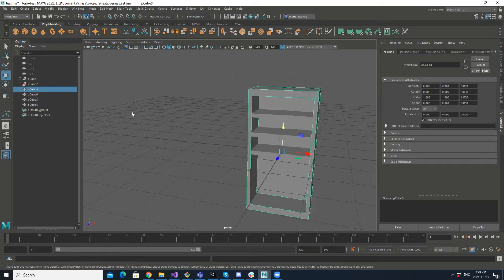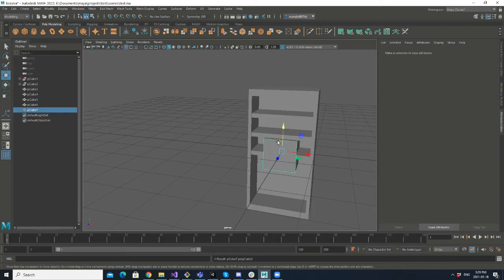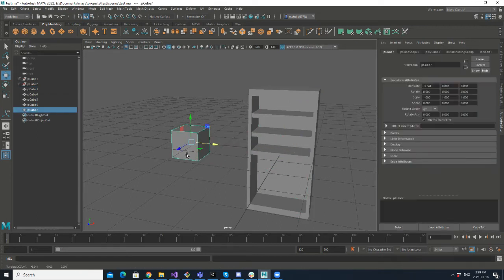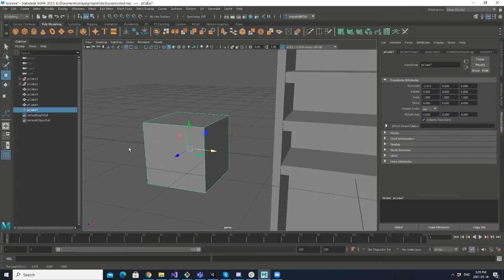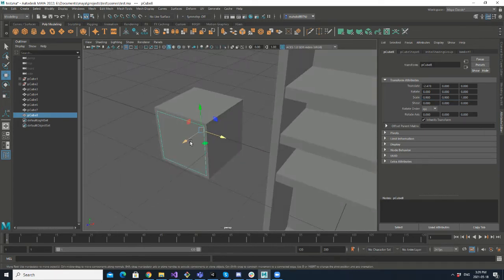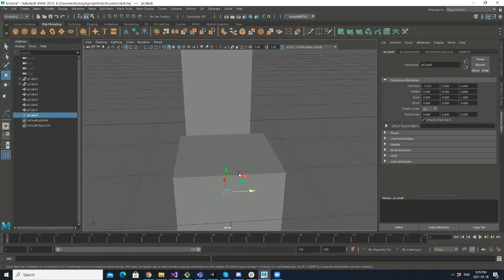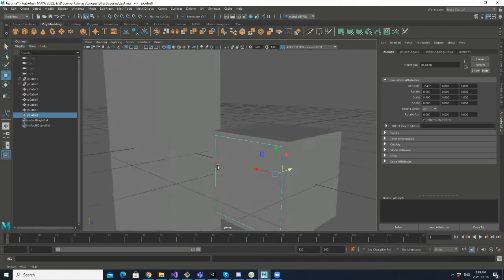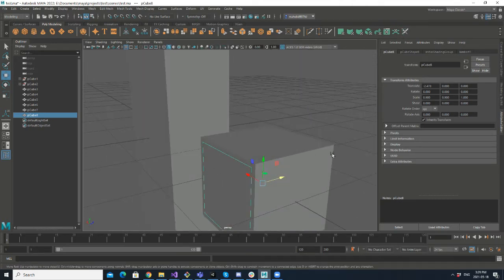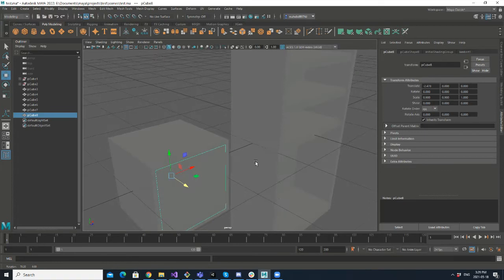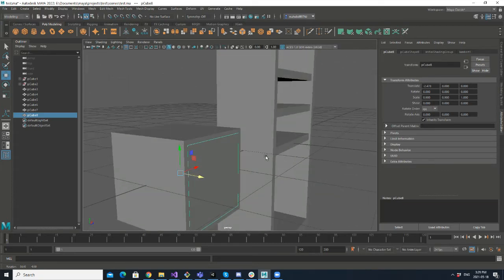Yeah, sure. So let me just create another cube. So let's say in this cube I want to make another hole. So I would duplicate it first and then scale it to something, for example, 0.9, 0.9. You can see it's kind of there. I would just bring it a little out, because if you don't do it, you may just make a hole that doesn't have any wall on the forward or backward side of it.